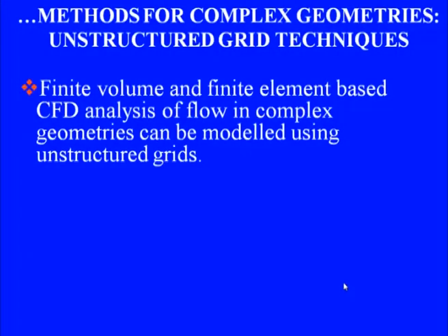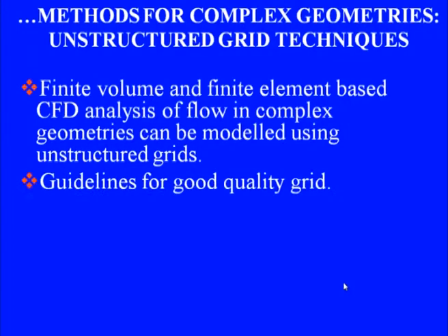Now unstructured grids we will primarily use in finite volume and finite element based CFD analysis, and we have to follow certain guidelines to obtain a good quality grid which can ensure that we get fairly accurate numerical solutions to a mathematical model. So let us have a look at these unstructured grid guidelines.